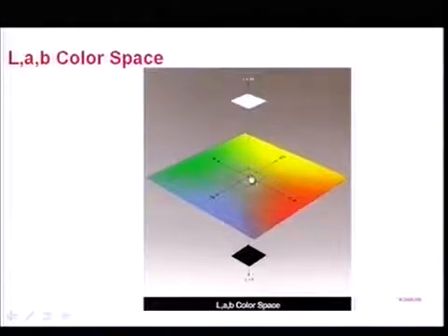So, what is the objective of bleaching? The objective of bleaching is to remove the color. In a mixed office waste, you have multi-color present there. Depending upon what color paper is coming in, if you have a lot of telephone directories, yellow pages, you are going to start with yellow color. A lot of ink like newsprint, flexographic ink, at the pulper it is going to look like you are going to start with the blue color fiber.